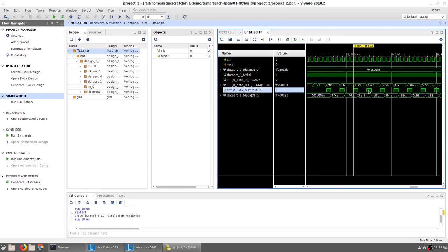The important thing to keep in mind is this was precisely the part that was automated in the C test bench, where what it did, rather than looking at the exact values that were being generated, was to compute the norm of the output, the difference between the expected output and the actual output, and check that it fell within an acceptable tolerance value.